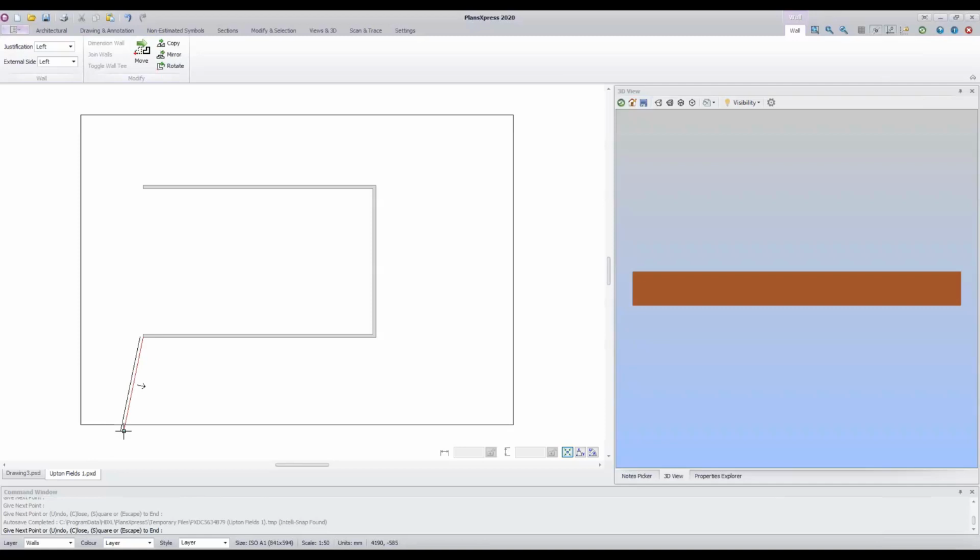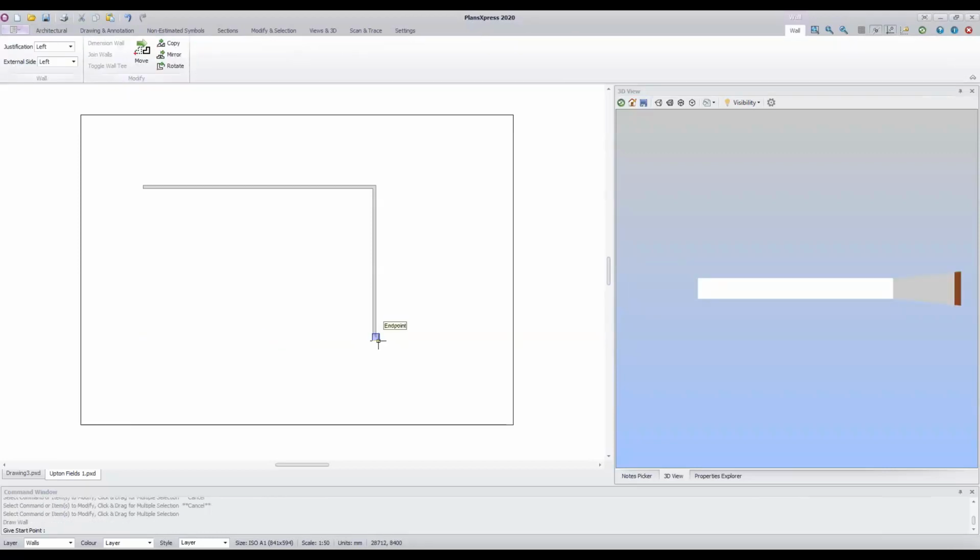I will just show you how to do that once more. I'm going to delete that wall. You can leave your walls as they are for now. I'm going to just repeat that process so I can show you how to do it again. So we hover our cursor over the end point on the wall we drew first. It turns pink. Wait for it to turn pink. And then if I slowly move my cursor down, you'll see we've got that line connecting the first point with the point we're about to draw. Hold down the Shift key to make sure that the wall we're drawing is straight, and then left click to place that next point on the wall.